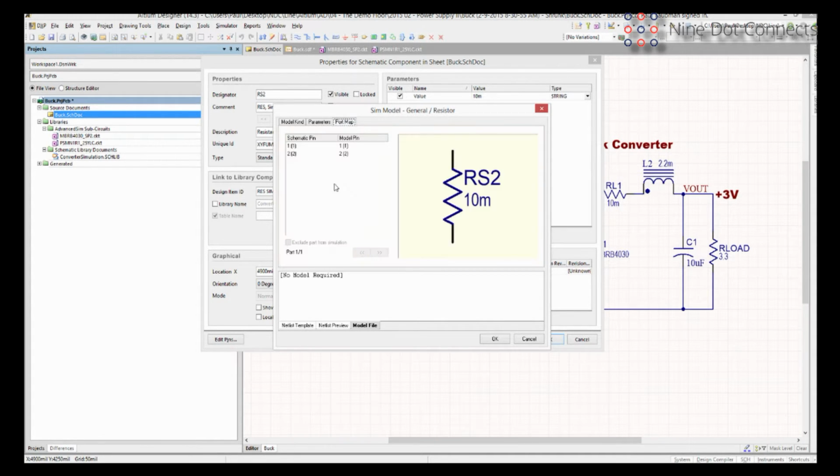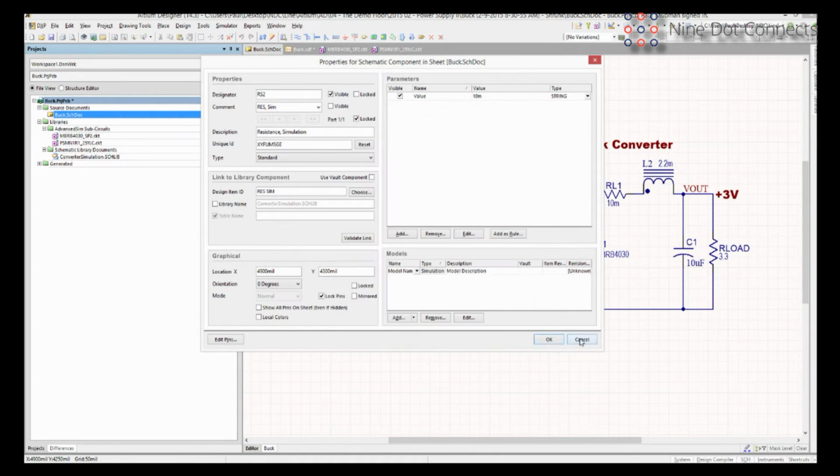And then lastly, which is very important, is your port map. Now in this case over here, it really doesn't matter because we're dealing with a passive, and whether the component is flipped or not is not a big issue. But you'll see in a moment where your pin mapping can be very important, especially if you've got very specific ins and outs of a certain component like a FET or something of that nature. So that's all been set and done here.